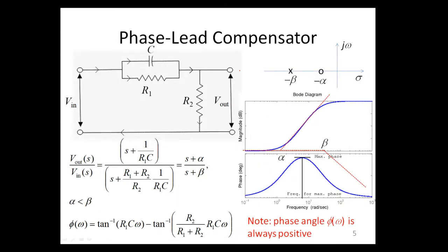This slide illustrates the hardware realizations of the phase lead compensators. As you can see in these figures, a phase lead compensator can be achieved using RC filters, which consist of two resistors R1, R2, and a capacitor with the capacitance of C. The transfer function of these RC filters is clearly shown here, and for the derivation you may refer back to the instrumentation low pass or high pass filter that you have studied before this.